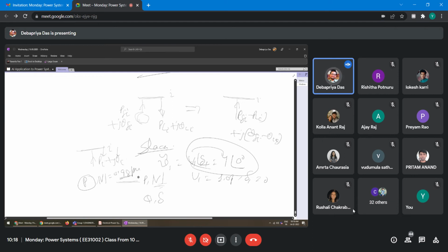If it is the ith bus, then Pi and Vi are known, and Qi and delta_i, these two quantities, are unknown. So in this case, voltage magnitudes are specified, and you have to try to maintain the voltage magnitude. But let me tell you, in a real power system it is really difficult to maintain the voltage magnitude. By putting some reactive devices there, we try to maintain the voltage magnitude at the bus, right? So P is known, voltage magnitude is known, but voltage angle and reactive power injection are unknown. That is called a PV bus.